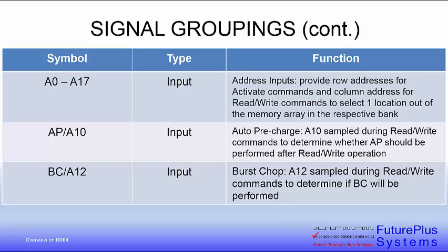AP/A10 stands for auto precharge. This signal, when sampled high during a read or write command, determines whether auto precharge should be performed to the accessed bank after read or write operation, and auto precharge closes the bank.